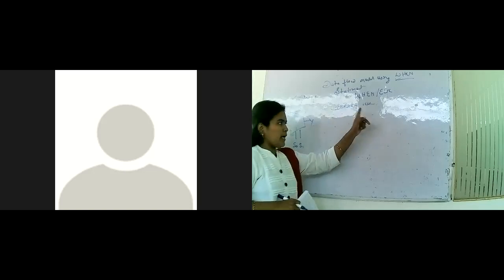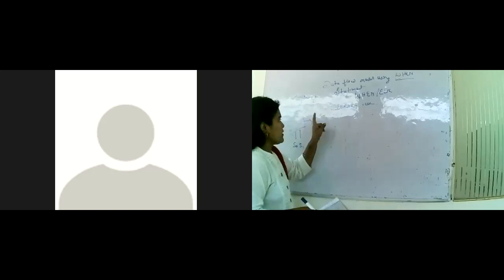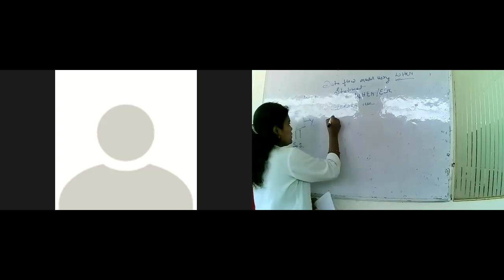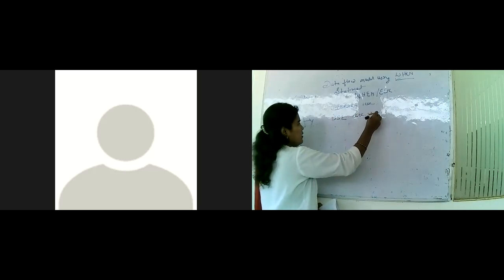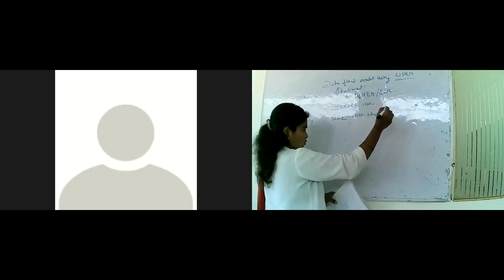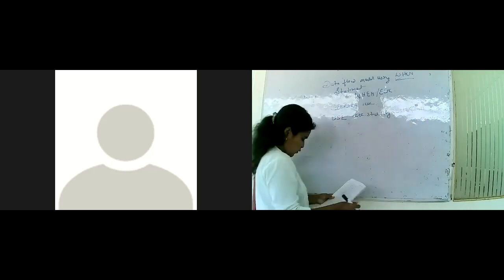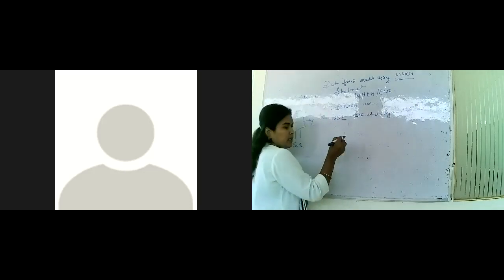So now I am writing the first section: library. For the library you are having two lines, one is library and the next one is use. Library IEEE; use IEEE.std_logic_1164.all. Okay, so this is the library section.